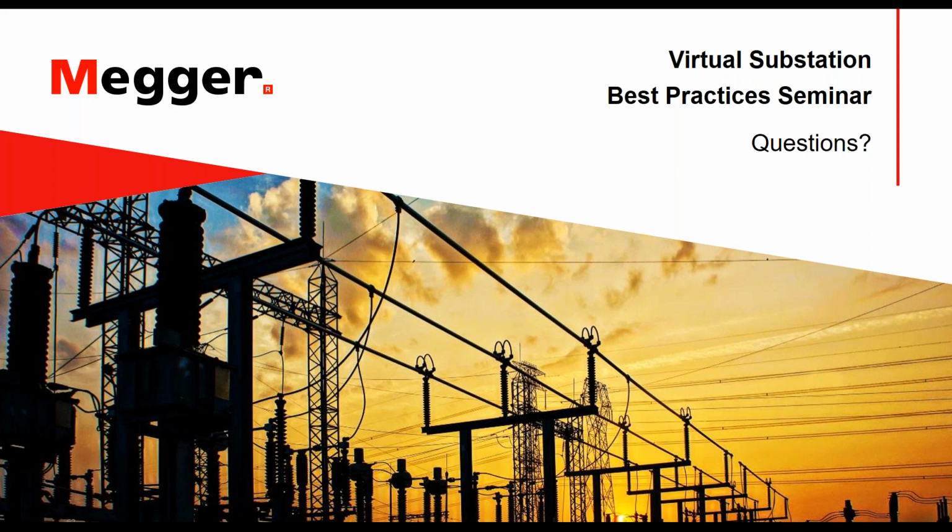So I highly recommend against using 10 kV equivalent values when you're trying to compare excitation current values. You want to compare test values performed at the same voltages.